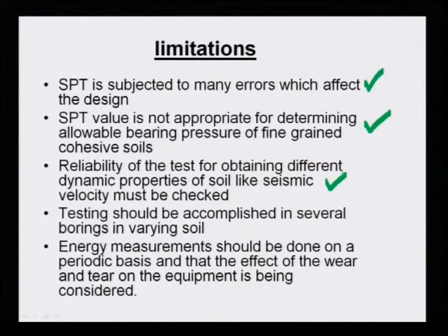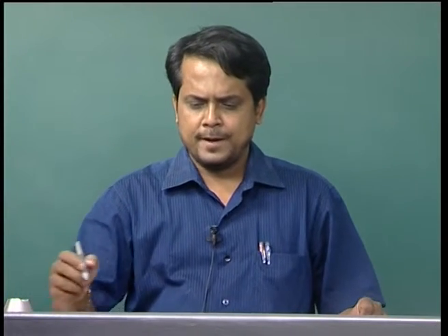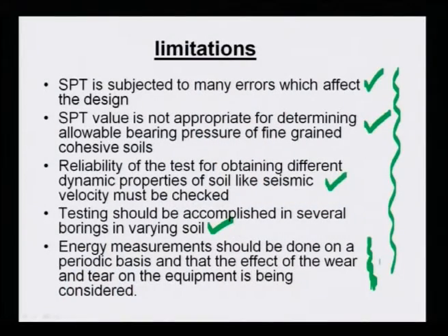Testing should be accomplished in several borings in varying soil. Before arriving at the value of N, you have to do a lot of tests in several borings, and check the energy measurement, because in these energy measurements corrections are also required. Despite several limitations, the standard penetration test is the most popular to get N. From there you can get phi, and indirectly you can also get the bearing capacity of footing.